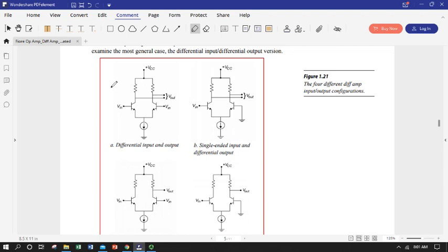And that brings me to just a general rule, especially for those of you who might be going on to classical engineering studies. Things tend to be linear when they're small. And this is something you may have used if you studied calculus when you looked at deriving the equations for derivatives for different functions. If you take very, very small steps, even a very nonlinear function can look linear over a little tiny increment. And that's the same kind of principle that's allowing us to use superposition, even though obviously we have semiconductors where current voltage relationships are anything but linear. We're using very small signals and we're using ranges where that assumption is approximately true.